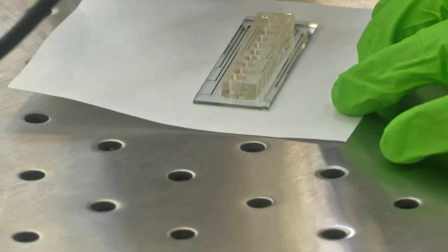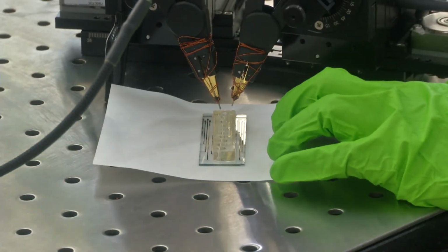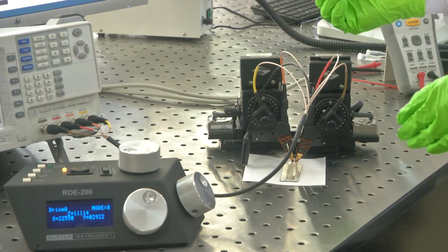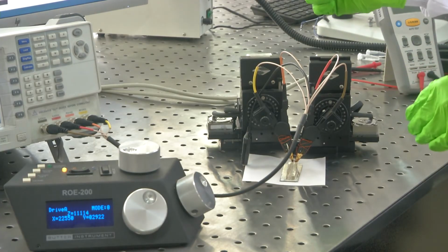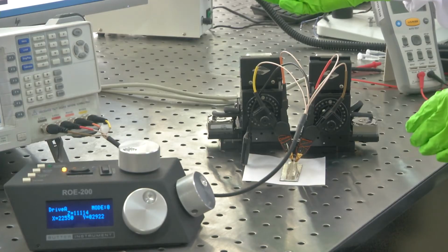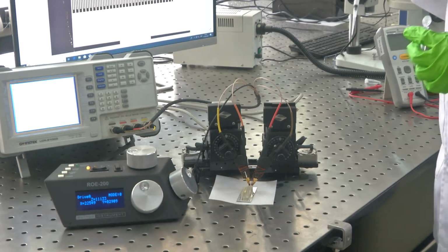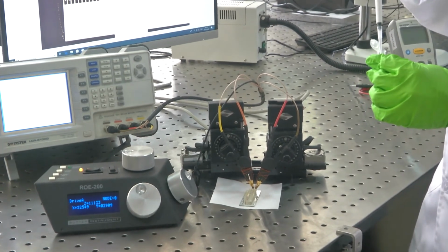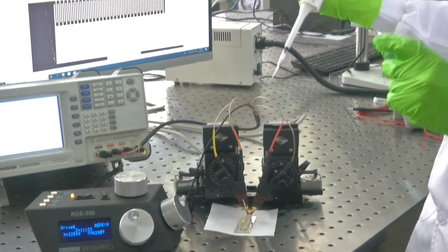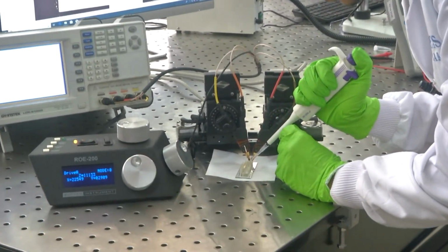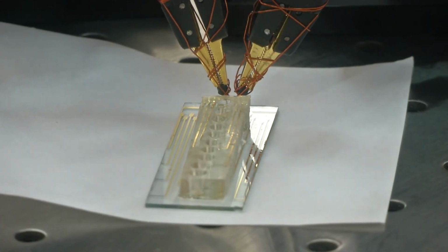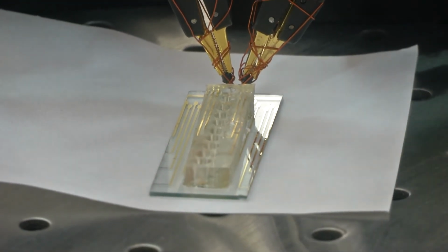Now I am going to connect this interdigitated electrode to our micromanipulator with the probes. Now I have connected the microchip to the manipulator. I will be loading a sample solution into this chip right now, and I will show you the measurement on the PC screen as well as the impedance analyzer. After connecting the microchip, I am taking a micropipette and pipetting 50 microliter of salt solution as a test specimen, and I am loading it onto well number 1. Now we will be measuring the impedance of the well.